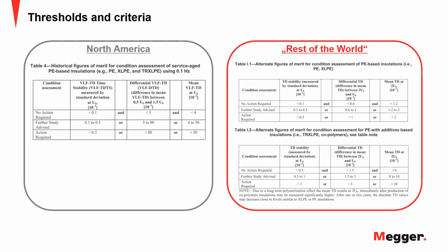As I explained, you have a falling tan delta. So it's funny, it's getting better with age, right? And that would be the impression you get from that. You have the influence of the accessories. You have the technology of the joints. You have the cold shrink, heat shrink, slip on.